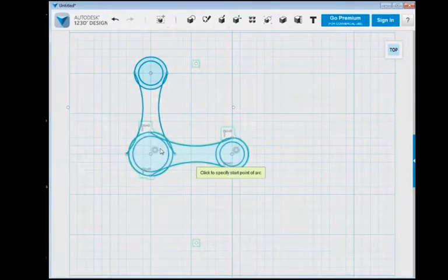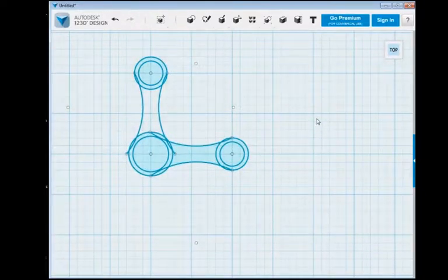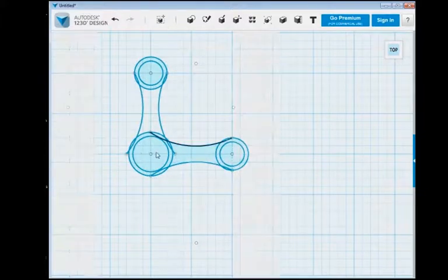Okay, I'm going to click the green checkbox to exit and deselect. Now you'll notice two different things. One is the horizontal arm is all blue. Blue, green, whichever color you want to call that. And the top arm is not. Both arms are identical, but you'll end up doing a lot more work having to merge all of these pieces together because we made this in three different sketches. We have one sketch up here, one sketch down here, and a sketch for the arms.